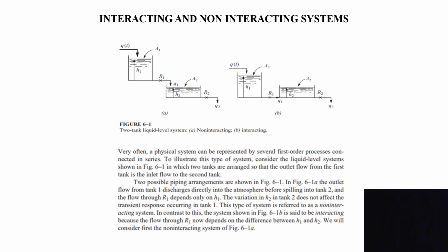When you take the second one, the level in the first tank is going to affect the level in the second tank, as well as the level in the second tank is going to affect the level in the first tank. That's why it is called an interacting setup.